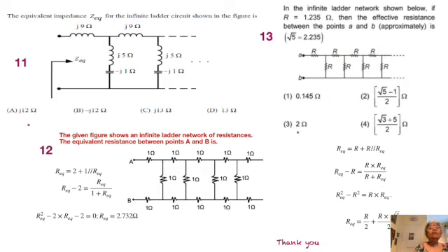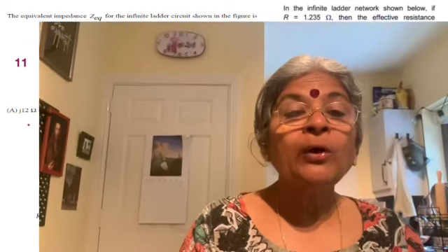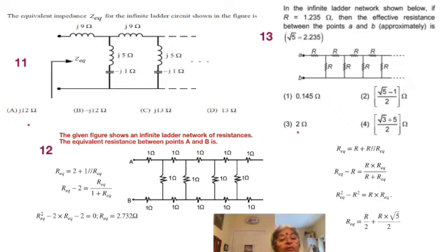Here I would like to say something else, in the sense that when you have J4 in parallel with something, the value of the parallel structure becomes less than J4. So in other words, the total ZEQ, if you look at it from the left side, is equal to J9 plus a little less than J4. So it has to be a little less than J13.